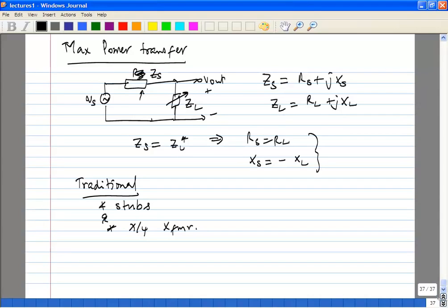What is the maximum power that can be transferred to ZL? 100%, but what is the condition? ZS is 0, right? Both RS and jXS being 0 gives you maximum power transfer, because you get the total voltage VS across the load. That is a trivial case, but it's not so intuitive to many people. You have to know which one you are varying.